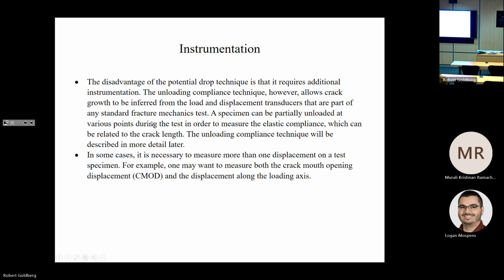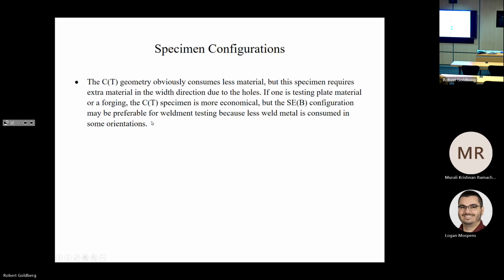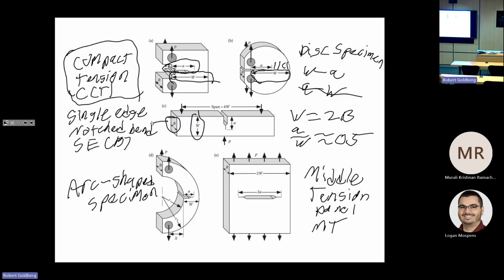So this compact specimen we talked about, here we go, this compact specimen can be designed so that the load line displacement and the crack mouth opening displacement are identical, but these two displacements don't correspond in this specimen here, because the mouth will be opening horizontally and the crack will be opening vertically.